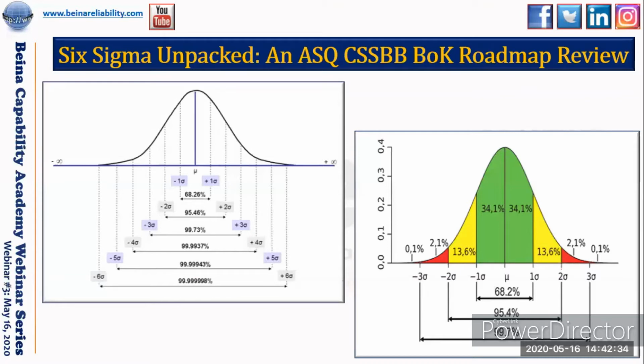But if you are operating at 2 sigma, which is between plus or minus 2 sigma, you see 95.4%. This is a massive jump. And if we move on to 3 sigma, you have 99.7% probability of not having a defect. So your defect probability is 100 minus 99.7. Low. That's why we said DPMO for 3 sigma, you saw it was, I think, about 6,000.